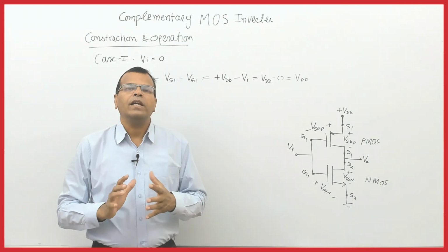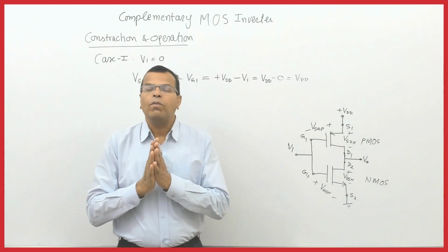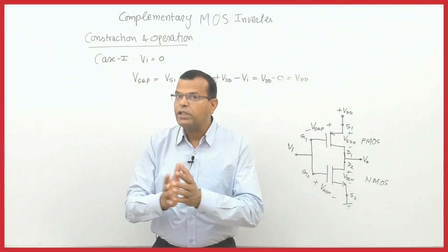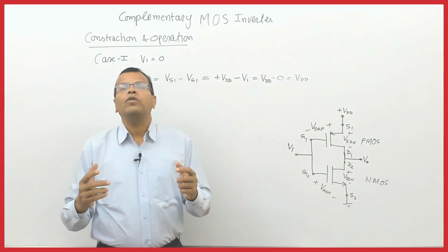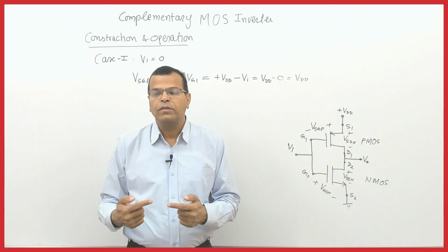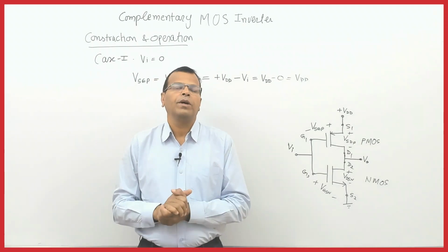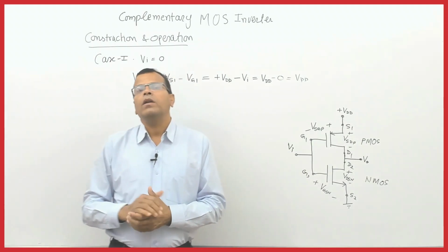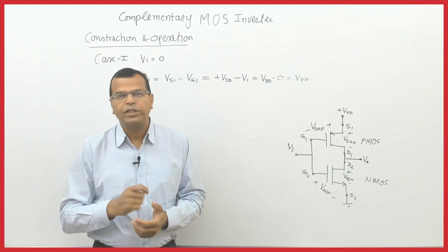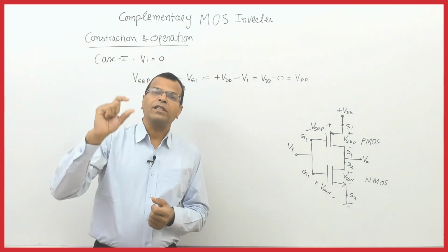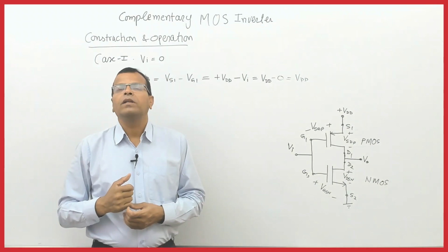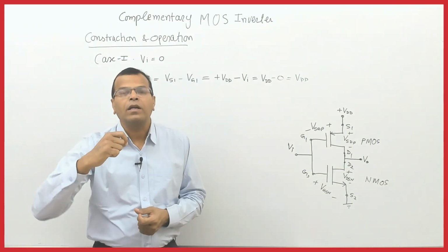So in this case, when MOSFET works in cutoff region, it will be like an open switch. When it works in ohmic region, it works like a closed switch. But remember, when MOSFET works in ohmic region, it is not a simple short circuit as a closed switch, but it is a resistive switch.